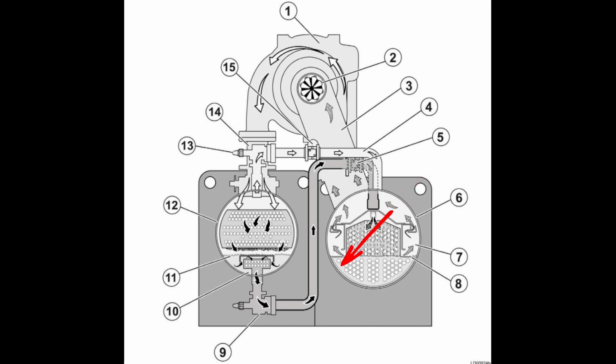So where the oil recovery ports for the eductor are located on these machines can vary quite heavily. They could be far more towards the bottom. They could be up more at a midpoint. They could be somewhere in between there. They will be located in a few different locations, depending on that specific chiller's evaporator and where the manufacturer expects that refrigerant level to be.